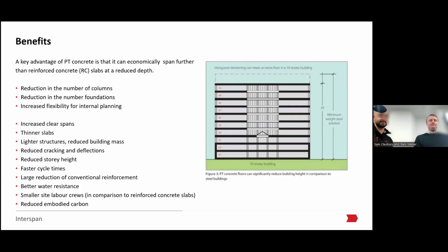And then, typically speaking, reducing it to reinforcement, Gary, you'd probably have half of that versus a traditional RC slab and a PT slab. Yeah. And then the amount of tonnage of post-tensioning relative to that is relatively low. Yeah. But the total amount of steel is much reduced.